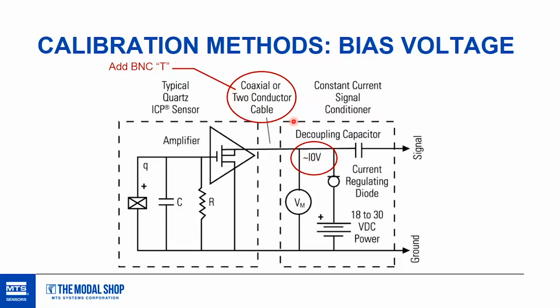So, why is it important? What is this bias voltage? It's another data set, another data point that you can get on your sensor, and it provides a little bit of health information as to how that sensor is performing. And the advantage that you get most of the time is that over time you can trend the performance of that sensor with respect to bias voltage. And what you can see sometimes is damage to that sensor, not on the bottom, but usually around the weld point, or if you have an epoxy sealed accelerometer, you can detect damage to that epoxy.